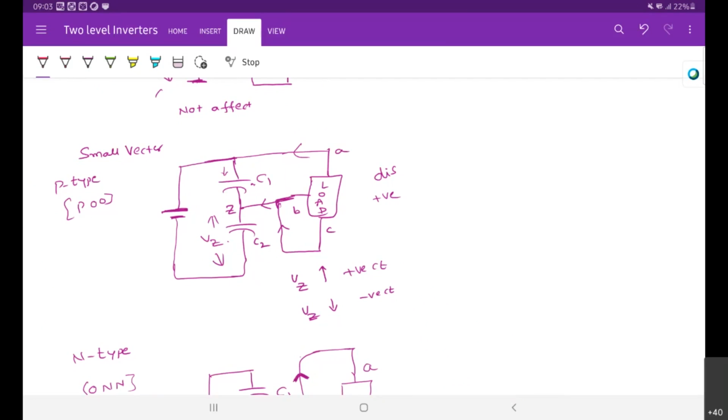See, in many applications, you may have a doubt about why these two should be constant. The sum of these two capacitor voltages must be constant, right? Our idea is to control the individual capacitor voltages. For example, this is 600 volts. The sum of the two capacitors must be constant, and the difference must be equally divided. You must get 300 on the top capacitor voltage and another 300 on the bottom capacitor voltage.